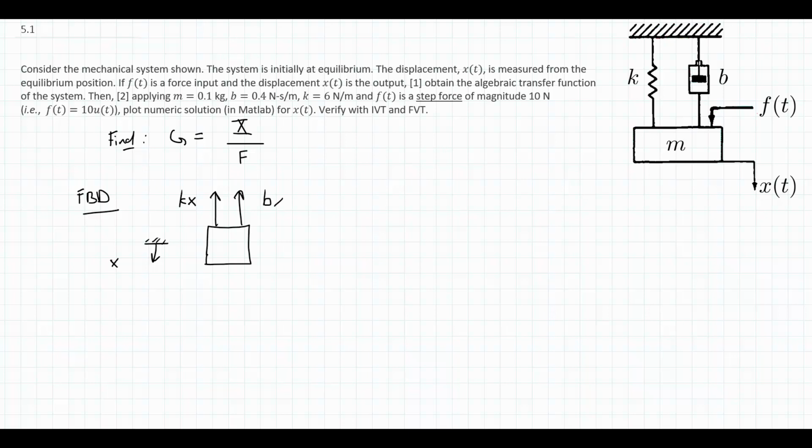So this too should be a positive x dot. So a positive b times a positive x dot. When the velocity is downward, it's being put into tension. That agrees with how we drew the arrow. When x dot is negative, the mass is traveling upward, putting the damper into compression and making this quantity negative, which again agrees with the way that we drew this.